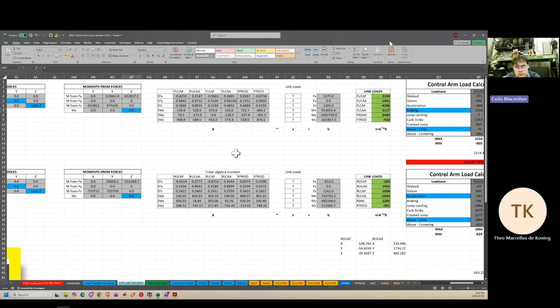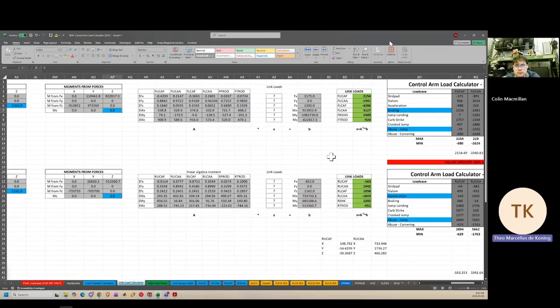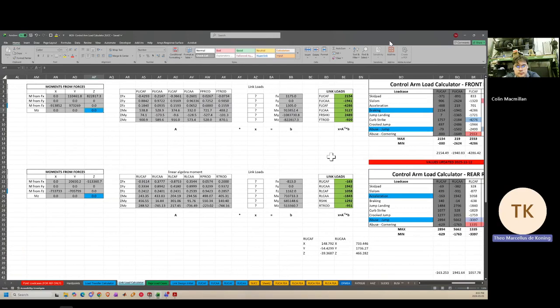It would be like using a wheel force transducer to get the tire data. Yeah, it's basically how the tire folds over and deforms as you're cornering. For the Formula car, they get their tires directly from the manufacturer, which provides that data. I don't know. Yeah. Not as important for off-road because of the low grip environment.